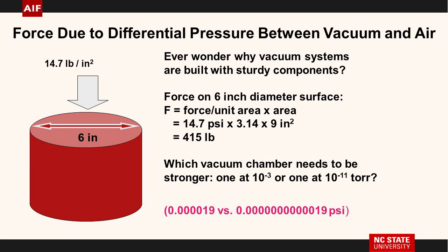So that tanker car, they only went down 0.52 psi. We're not even in the low torr range. We're not at 10 to the minus 1. So in terms of checking out a system, if you want to see if it's going to survive, you just need a forepump to be able to do that.